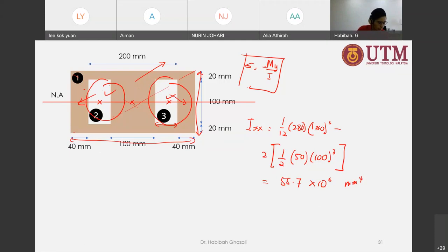So you use the bending stress formula to find the stress for steel. Steel is going to be at the top or the bottom, it doesn't matter really. We will just do the top part. You can do the top or the bottom, you just put negative or positive because they are symmetric.